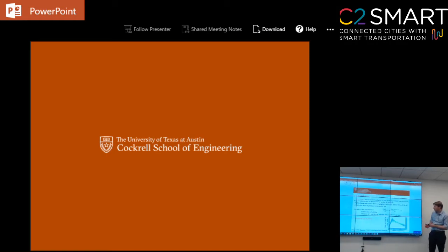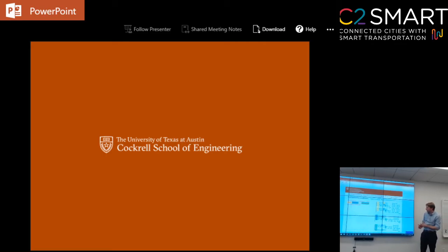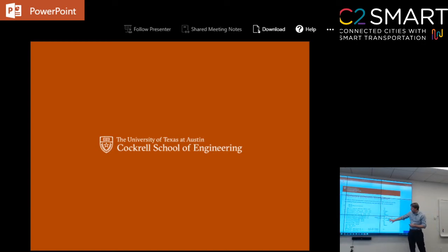If you write a certain network problem, like this example here, you have to assume that every beginning and end of the link is controllable to get an LP. If you don't assume that every single thing is controllable, for example, if you have highway sections that go into each other, of course you cannot control every section. You don't block traffic. In that case, you get a MILP. So how do you handle the weaving section? In that case you can still do it, but it's going to be a MILP. So you will have integer variables that will appear.